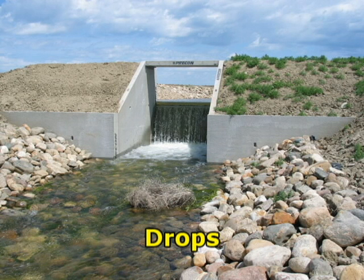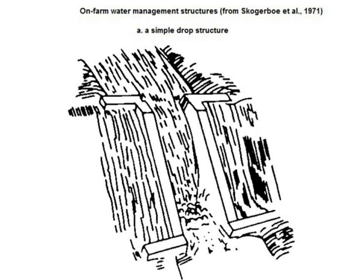Drops. Drops are placed in a ditch or canal to hold the velocity of flow within allowable limits, to increase the head on turnout devices, or both. Velocity limitations for irrigation, ditch, and canal standards are described in the technical guide.